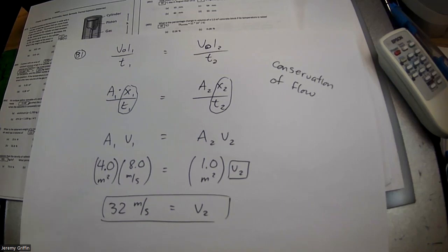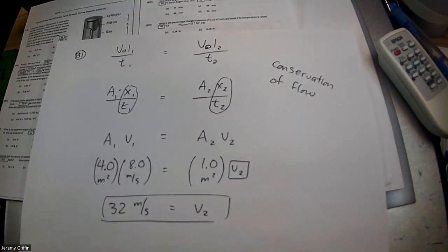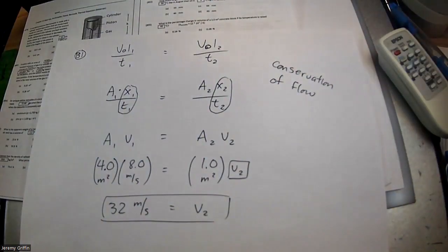How about this? I'm going to take this page of notes. I'm going to blow a stream of air over the top. Okay. And when I do, it's going to do one of 2 things. That moving air, either it's going to push it down or it's going to vacuum it up. Do you guys remember which way it is? Let's see. Do you guys see it vacuuming it up? Okay, so I blow a stream of air over the top and it vacuums it up. Wouldn't that indicate a low pressure? Okay, so moving fluids have a low internal pressure.